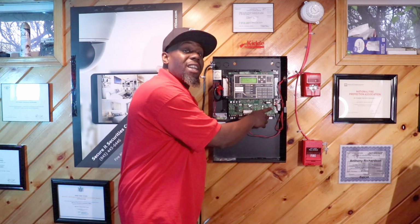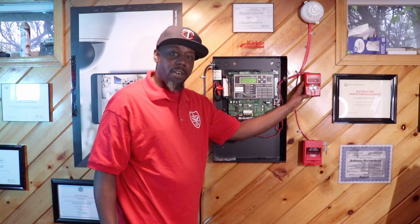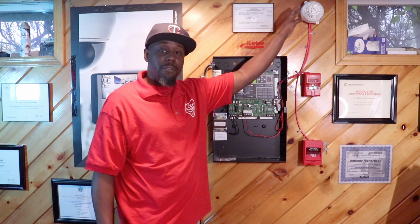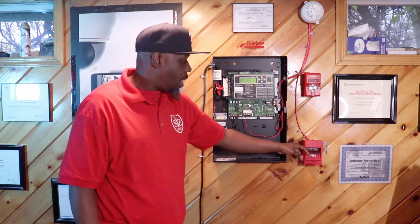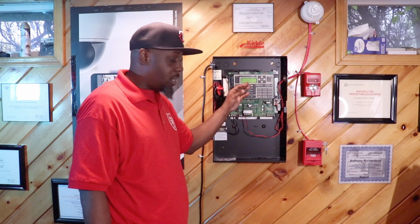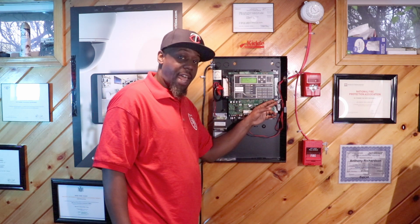Next, we have what we call the NAC circuits, or notification appliance circuit. These circuits connect to an output device, something like an LED strobe horn device. This will activate if the smoke detector senses smoke within the chamber, or if someone manually pulls the pull station. It will then send a signal through the fire alarm cables to the SLC loop, giving us an alarm signal. The CPU of the fire alarm system will then activate the output device, or the NAC circuit, to activate the horns and strobes to alert the occupants in the building that there's an emergency and you may need to exit as soon as possible.